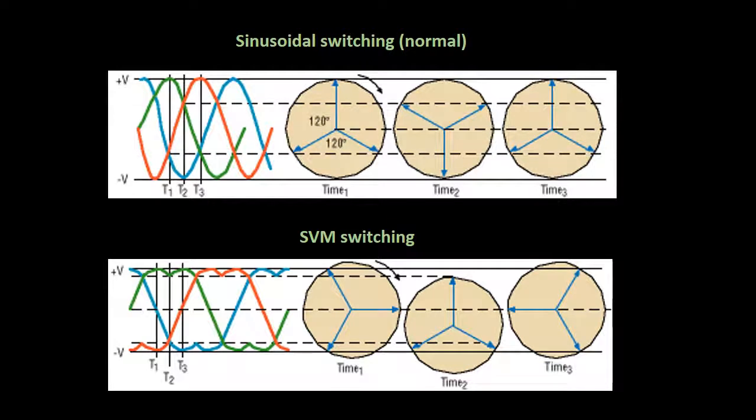You may also consider using more efficient switching patterns, such as space vector modulation over the standard sinusoidal modulation. Without going into the specifics, certain switching patterns can improve a VSD's total harmonic distortion and efficiency, as well as being able to cope better with varying loads.